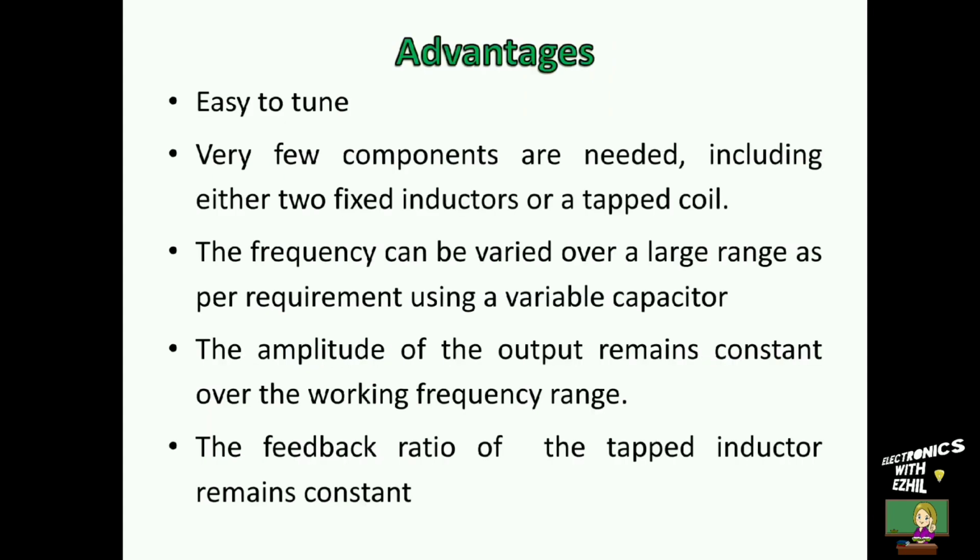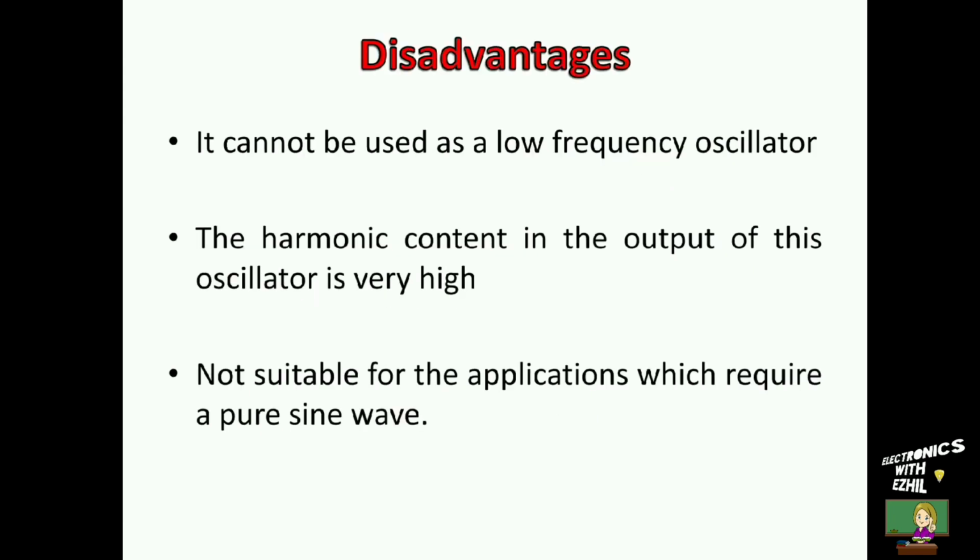Advantages. They are easy to tune. Very few components are needed, including either two fixed inductors or a tapped coil. The frequency can be varied over a large range as per requirement using a variable capacitor. The amplitude of the output remains constant over the working frequency range. The feedback ratio of the tapped inductor remains constant.